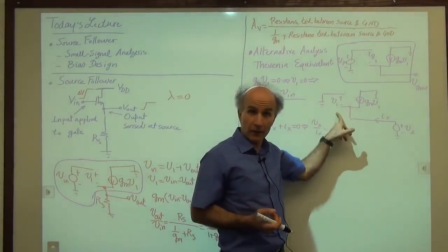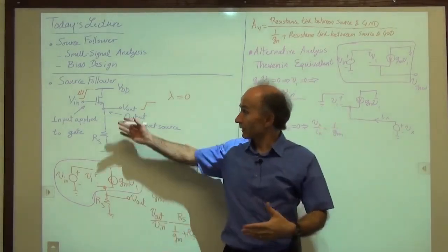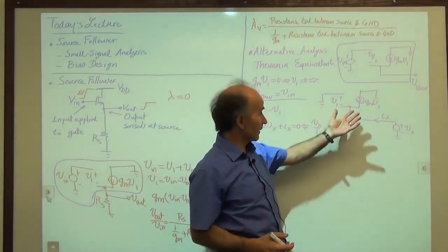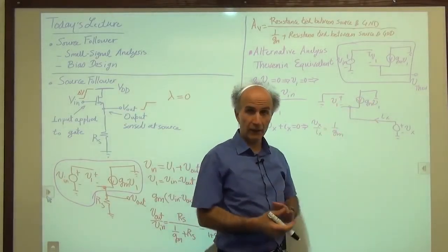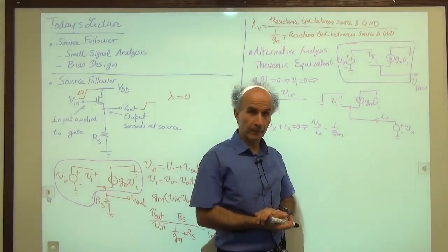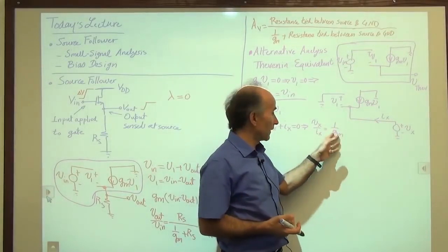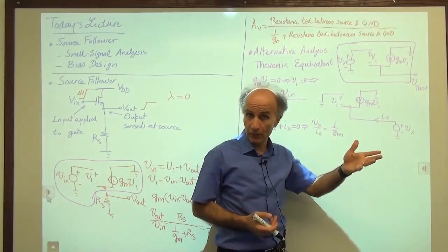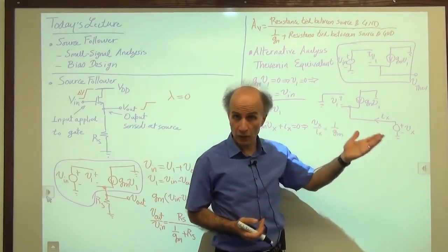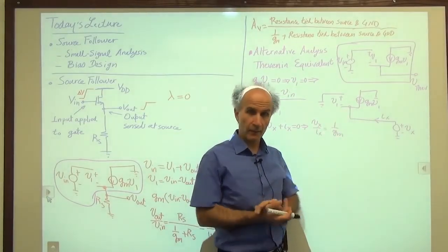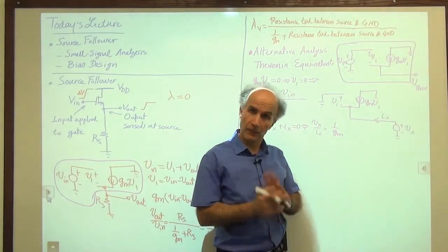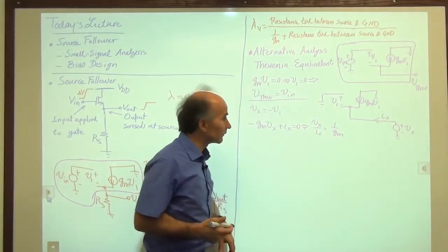So it is a diode-connected device, even though when we started out it didn't look like that, right? But in the small signal model, it is exactly like a diode-connected device. And the resemblance between this and the common gate stage input impedance is also not coincidental and follows the same type of thought process. But anyway, let's continue.